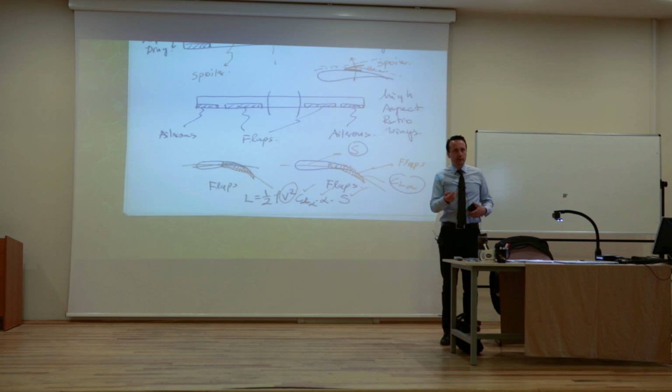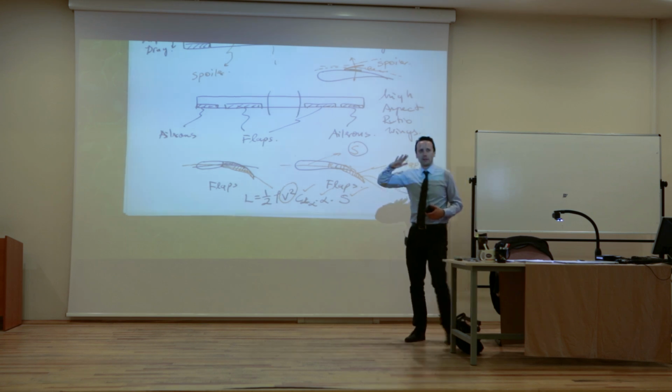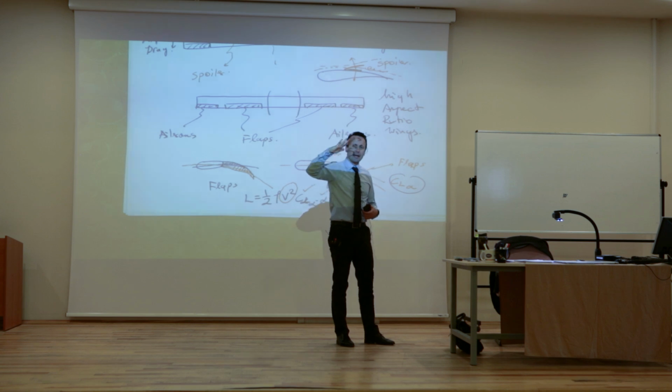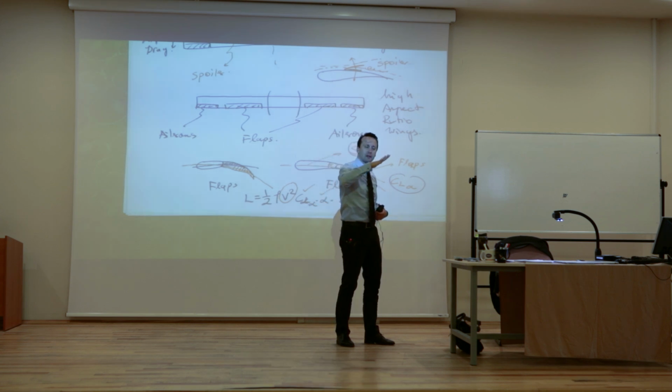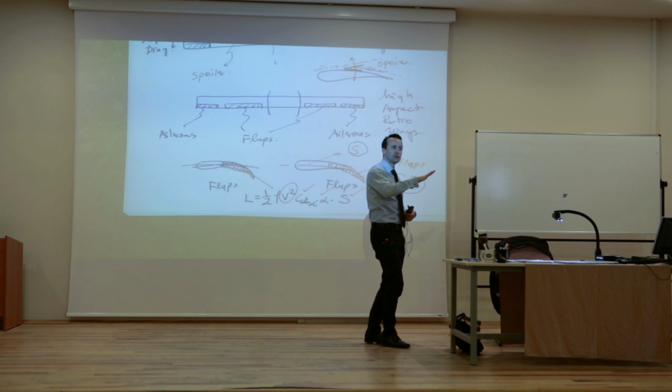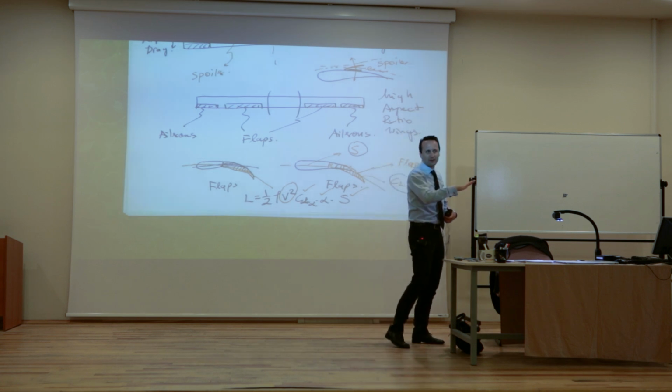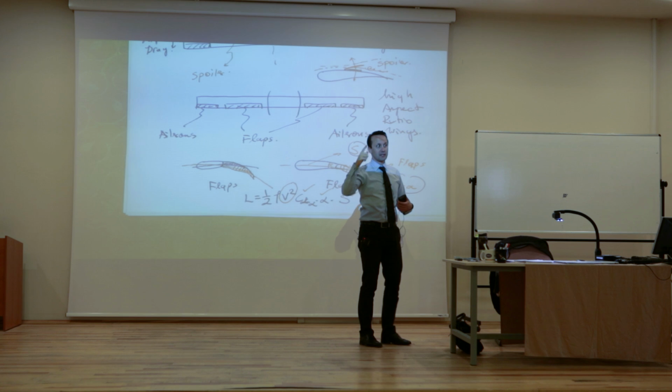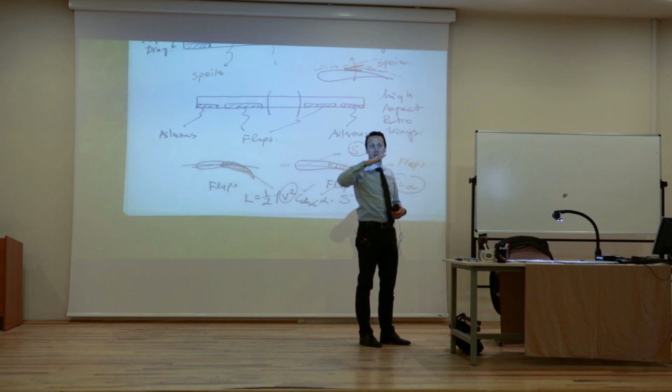You know, we had that discussion, I think. The lift should still be approximately equal to the weight while you're landing. That's always the same question, right? If an airplane is in landing and has no acceleration and constant velocity, is it in trim? Yes, of course, right? Which means the forces and moments are still equal to 0.